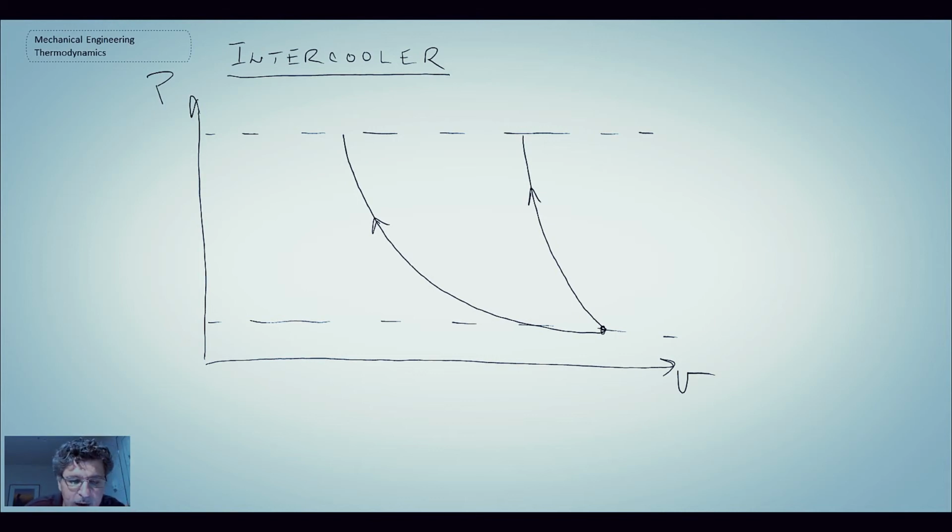The way that you'd figure out the polytropic power, the N value, is by doing experiments on whatever compressor you may have. Okay, so what we have here, this was isentropic. This here was isothermal.